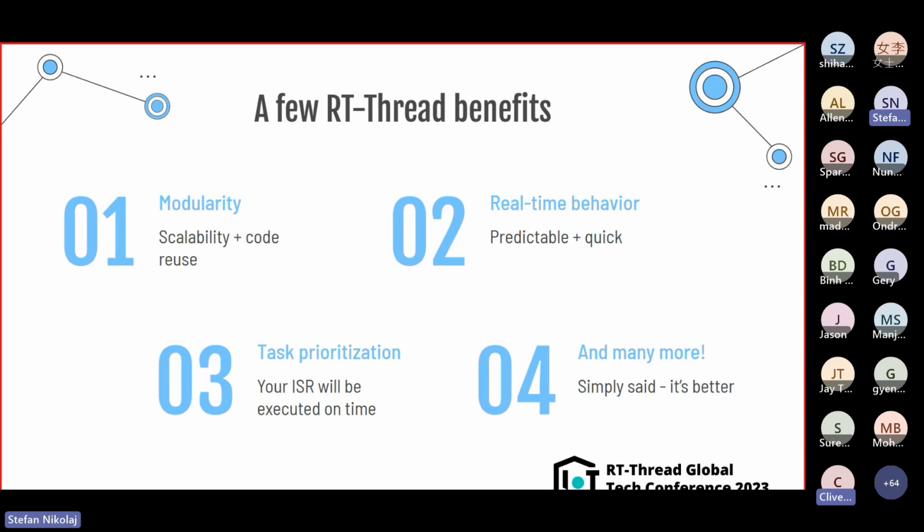It can happen, since I've seen developers never test the routines which are supposed to happen once in a lifetime, but shouldn't. And this is made worse if you're using a super loop, where usually for many microcontrollers you can only have one interrupt going on at a time. And doing that in software, as RT-Thread does, is much nicer.